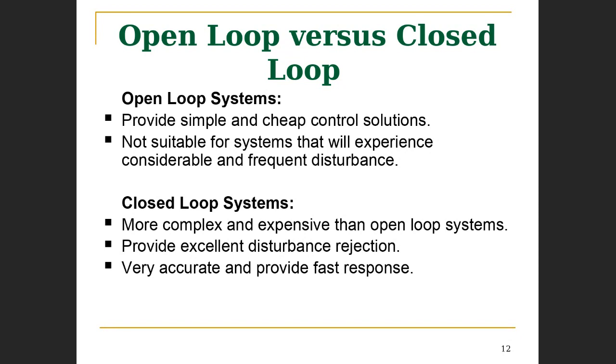You'll match the power of the drive system with the load on that belt, and that belt speed will be maintained throughout quite successfully without any problems. That's open loop. There's no need to measure the speed of the belt.